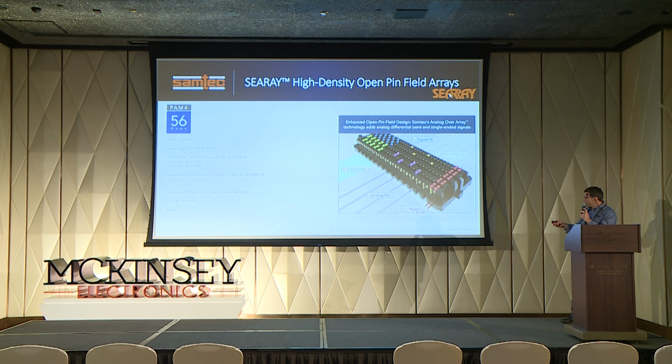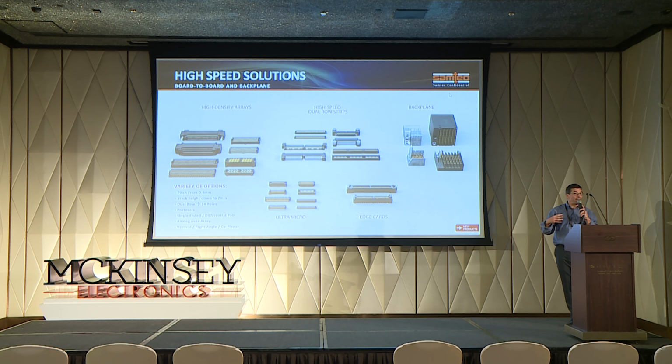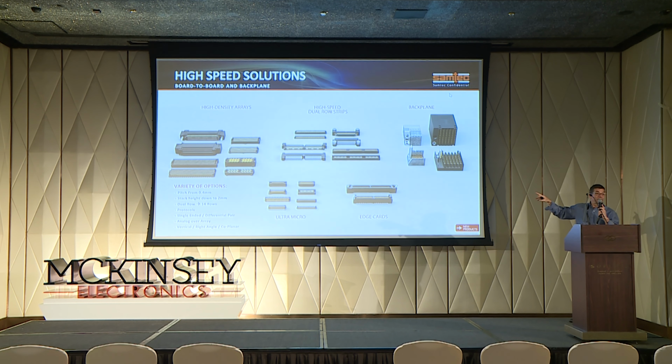We support edge card systems, which can be PCIe sockets up to Gen 5 speed, Gen 6 speed, as well as our HSEC8 high-speed edge cards on a 0.8 millimeter pitch. Really good, robust product. On the right-hand side in high speed, we get backplane. So we've got a license with Amphenol for ExaMAX, so we do a dual sourcing agreement, intermateability, and we can also build a bunch of customs based on taking sub-modules for power, signal, I/O, based on this solar system here, the Exceed HD. So we've got a lot of customization available in high-speed systems.